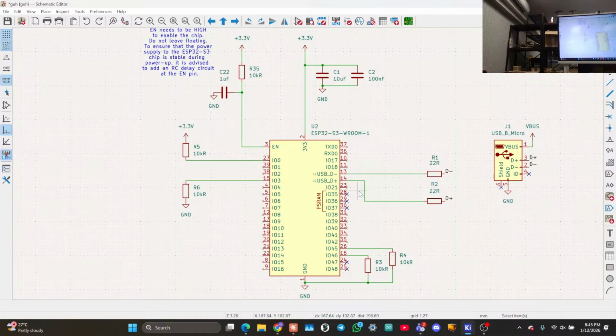If you want high impedance, the way you can think of it is that when you're measuring a thing, you will consume a little current. Measuring 3.3 volts will consume a little current. If it consumes more current, then the resistor will have the potential to drop voltage, and now that thing is no longer 3.3 volts. But you want it to stay roughly at the logic level. That's the actual reason.